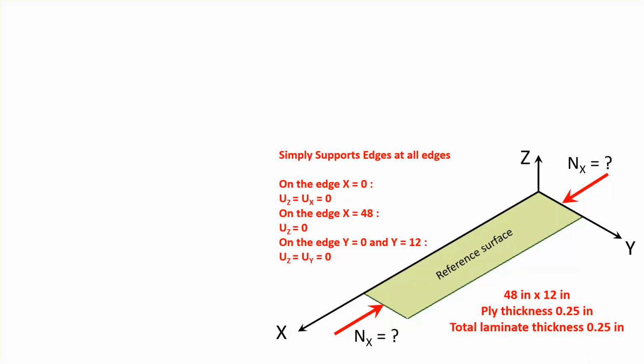This is a huge thickness, so you can imagine that these are multiple layers of carbon epoxy in the same orientation, which is 0 degrees, as you'll see, of much smaller thicknesses, and added together is going to give you 0.25 inch.